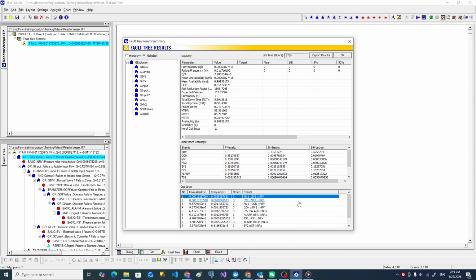The order of a cut set simply indicates the total number of individual basic events that make up that specific scenario. If you look closely at our list, you will notice that every single cut set has an order of 3. This mathematical output perfectly validates the physical architecture of our reactor vessel, directly mirroring the 3 independent layers of defense in depth we engineered into the system.